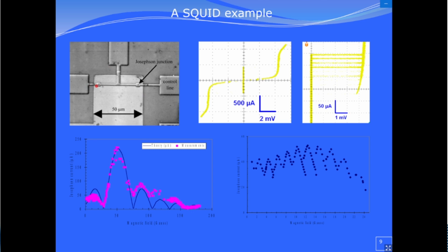These are the two dots here, 1 micrometer diameter typically. And we have a counter electrode with this structure. Usually to measure the IV curve, you just pass the current here. It goes through these two junctions, it crosses the tunneling barriers, and then goes back here.